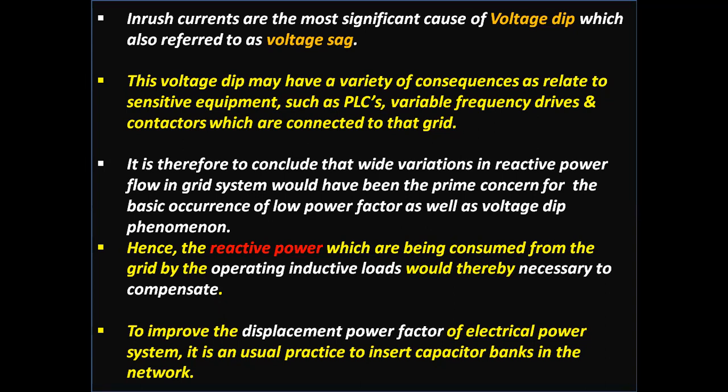Hence, the reactive power being consumed from the grid by the operating inductive loads is necessary to compensate. To improve the displacement power factor of an electrical power system, it is usual practice to insert capacitor banks in the network.